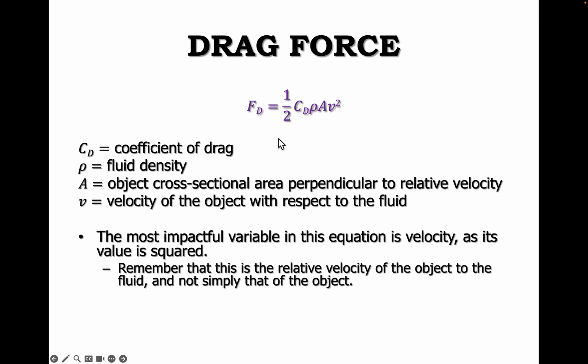If you wanted to calculate drag force, here would be the funky equation. A few different components of it: the coefficient of drag, which is CD; fluid density, which is P; the object's cross-sectional area, which is perpendicular to the relative velocity; and V is, again, the velocity of the object with respect to that fluid. If you look at all these different variables, since velocity is squared, the change in velocity is going to have the greatest impact on drag force.